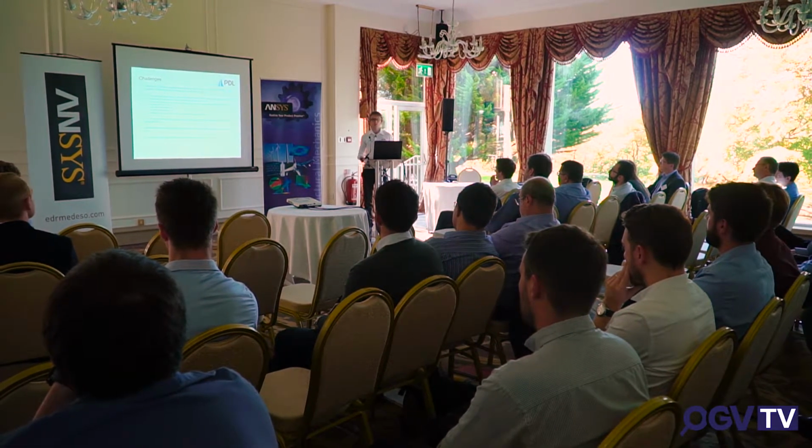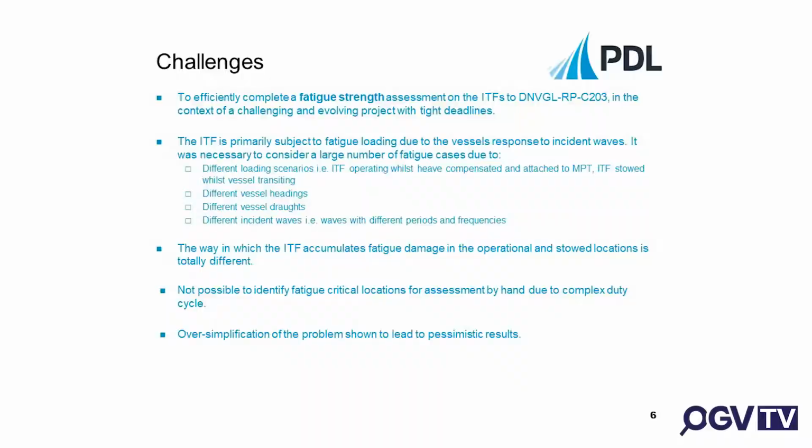But the problem here is we can't pick a representative load case, as there are too many. If we were to pick one, the highest stress wouldn't necessarily be the fatigue critical location. It would just be the highest stress for that one-off loading condition, but there are all these others. So really we have to perform the analysis for the whole structure. Also, what we found is oversimplification leads to over-pessimistic results, and you can't design an efficient structure. So you have to go to quite a high level of complexity to design something efficient, without wasting a load of material.